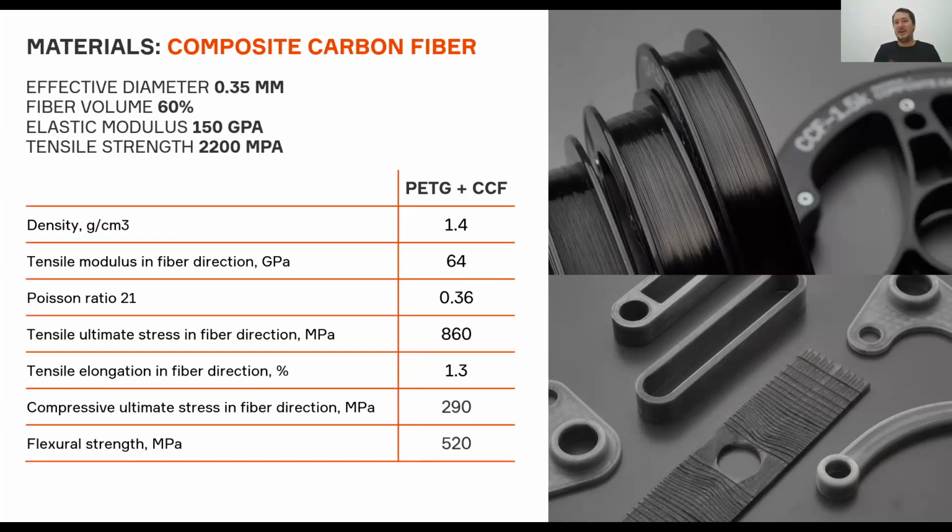And there are actually three options for free fiber placement that we have at the moment or will be able to offer in future. The first option is a tool separate from Aura, which is called Nanogy Code. It's a plugin for AutoCAD-type 2D drawing software, where you can manually define the fiber paths and then convert them into G-code. That's the one option that we have at the moment and that we can offer to our customers upon request. But there will be two new options.